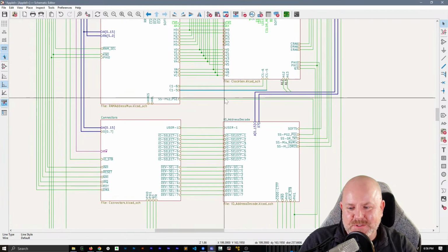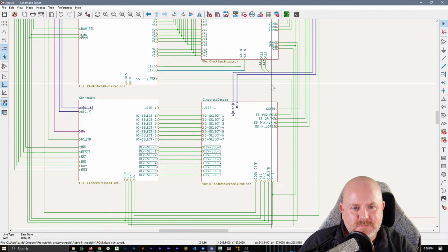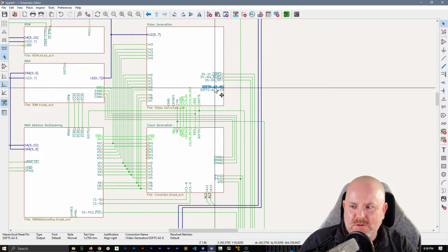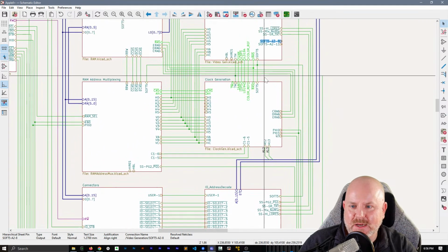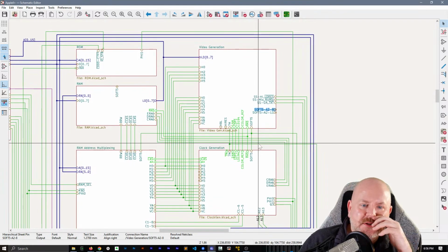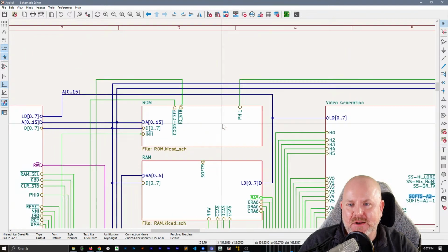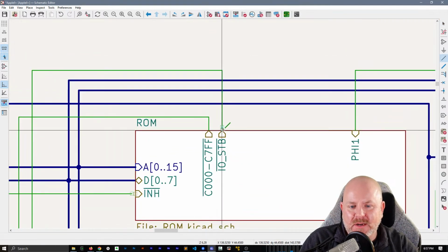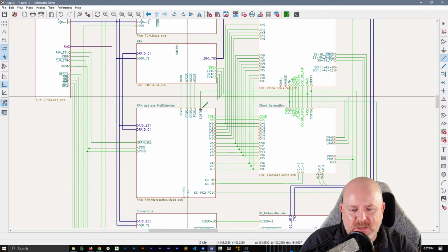Okay, what else is missing? Have I saved this in a while? That's probably a good idea. So I don't know where this... See, I never found these signals in this other guy's schematic. So I'm not certain. I guess we're going to have to go and figure out what these are, because I don't know where to connect those. But you know what? I'm really itching to run ERC. So let's run ERC and find out.